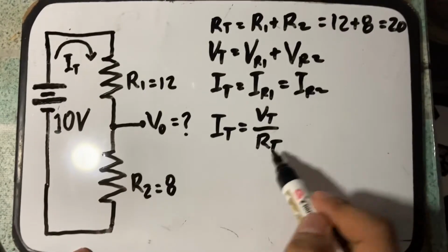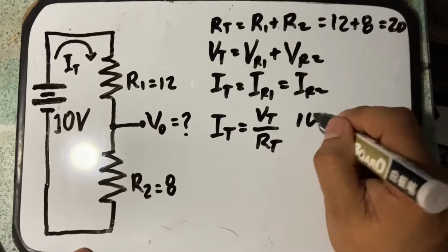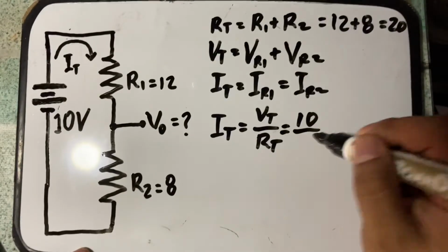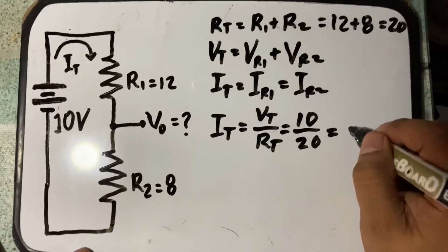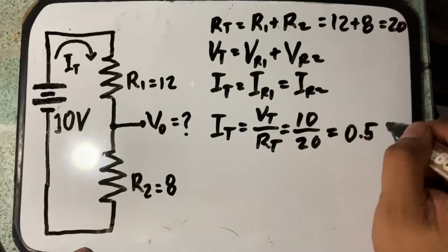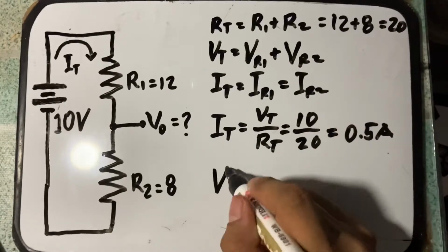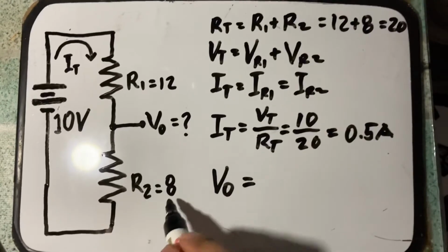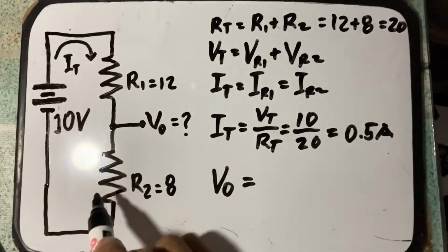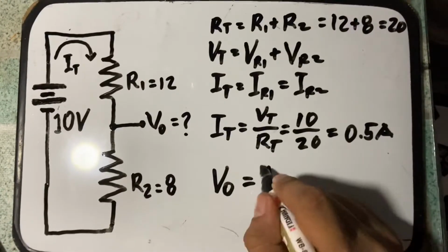So ang voltage natin is equal to 10 volts and then 20 ohms naman yung total resistance natin, which is equal to 0.5 amperes. And so we can compute for VO or Vout, which is current times R2, since alam naman natin na yung dalawang value na yun.